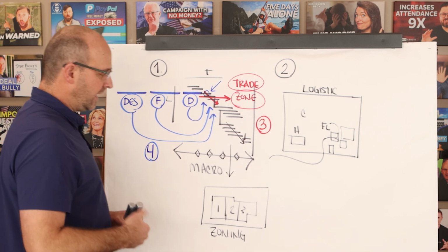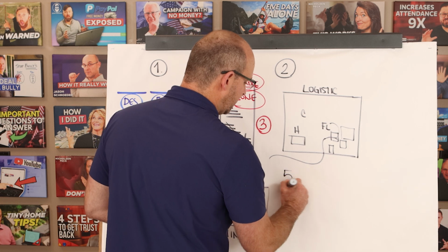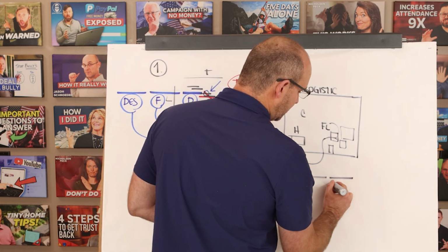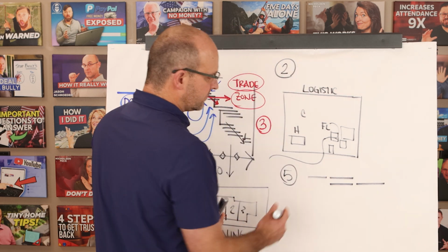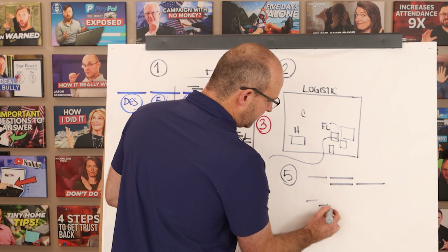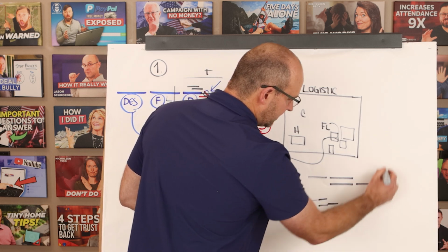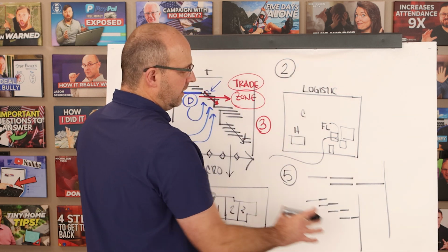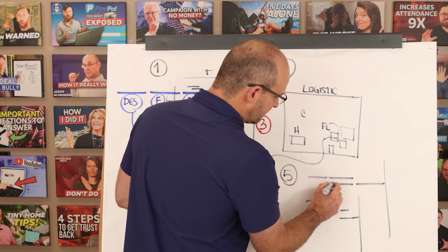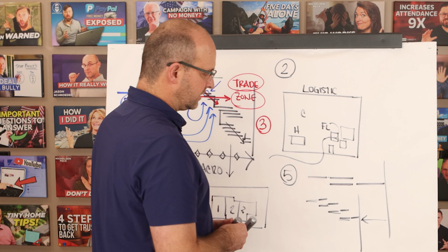And I tell you that because there's another secret. Number 5, you need to look at your zoning as a part of your project plan. Again, like I've shown you in previous videos, if you have a 2-zone strategy and you go to 4, right, then your overall duration will be cut in half, and then you will see that the overall duration for these activities takes less time, and you still have this duration plus this duration is the same down here, but the overall total project duration has shortened.